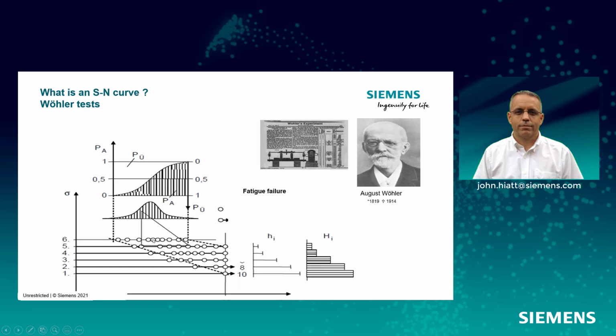And again, these material curves, for stress life, it's an SN curve. For strain life, it's an EN curve. They all do some of the similar tests where they're cycling and fitting. It's just the EN curve has a little more complicated shape because it gets more into the plasticity. They all have variations.